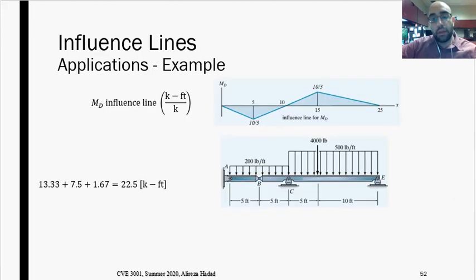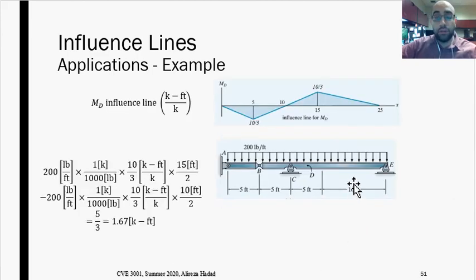So for that, all I can do is to just consider the beam weight in the whole length. Again, since it is a dead load, I don't have the option of distributing it in specific regions. It is always over there during the whole length of the beam. Now, based on this distributed load, what is the maximum moment that can be created at D?